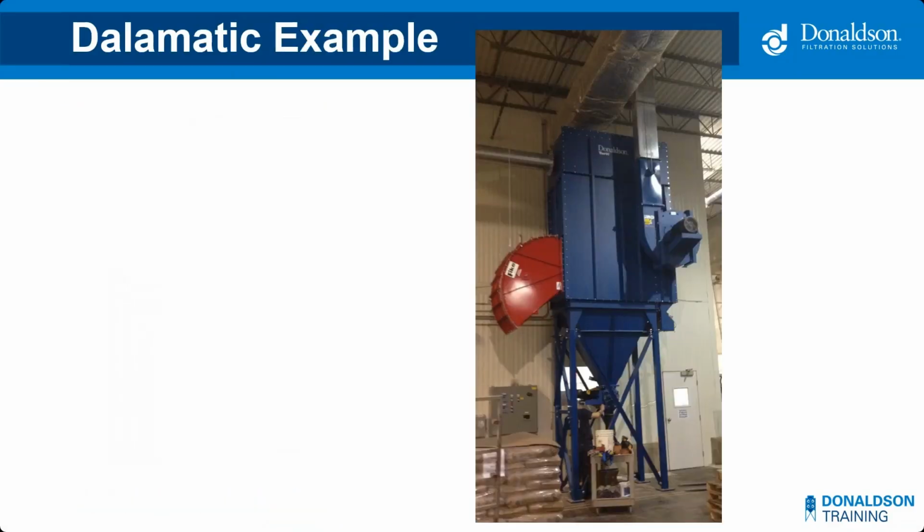All right, this is just an example of a recent Dolomatic install that was done. You can see like the DFE I showed earlier, it's got a flameless vent on it. That's because it's inside. So the flameless vent was required by the AHJ. You can see that the return air, however, is going through the top of the roof there and being discharged outside the building. And then over here on the left, you can see the control panel is relatively close to the collector, which is fairly common in most cases.